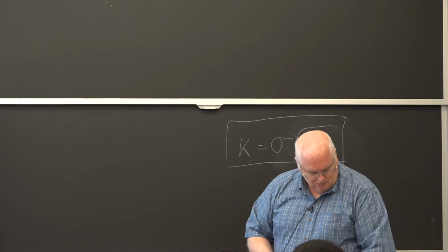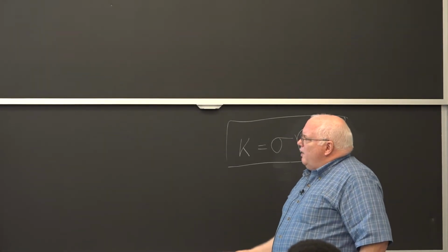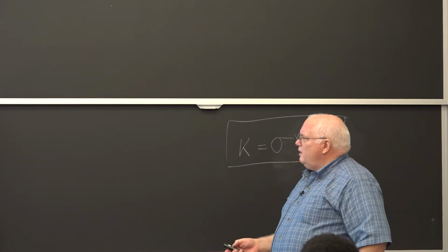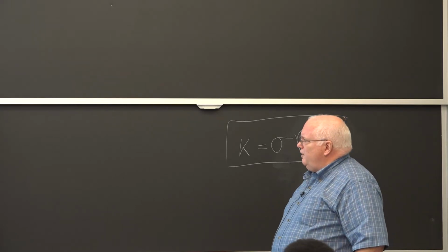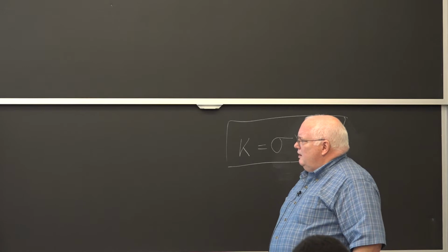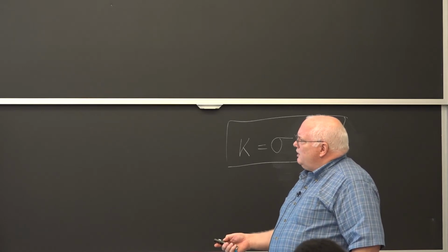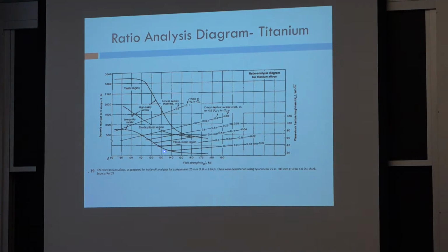It was originally, oh, I do have my pointer. All right, just looked in the wrong place. But anyway, Irwin was trying to study this because of the Liberty ships after World War II, trying to understand it and how to apply it. And he found he could use the fracture mechanics formula of Griffith from 1925. This was 30 years later. He applied it to steels and titanium. If you look at titanium, you find you have about 1/3 the toughness of steel, and the strength is actually about 2/3. Okay, the drop-off here is about 120 rather than 180 KSI.